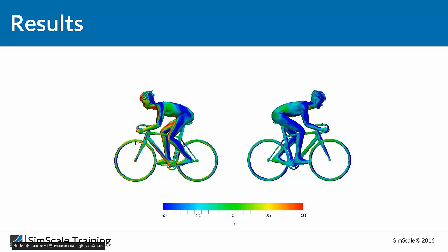I'm talking here about tires only, not the whole rider and bike geometry. That's why the thin tires can perform better in side wind, because you will not have as much side force as with the large tires, but actually they create so much drag compared to the large tires, and we will see this in the numerical values.